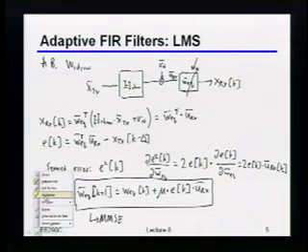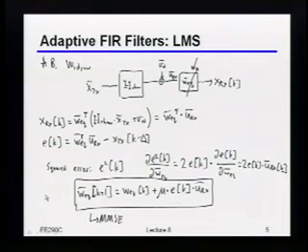Intuitively, this is a good thing to notice. What I'm correlating is the error at the output, which is after the equalizer, with the input to the equalizer. That input contains the noise, right? Back in statistics, whenever you multiply things and average them, that's like doing a correlation. What you're doing here is driving the correlation between the error and the input to the equalizer to be 0.